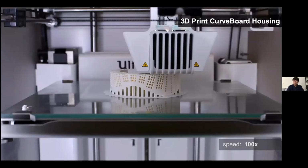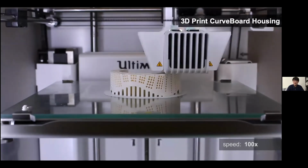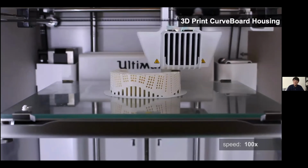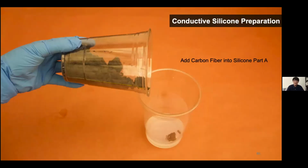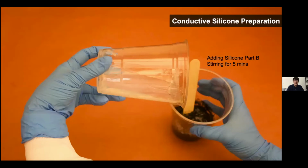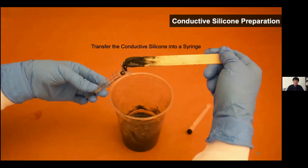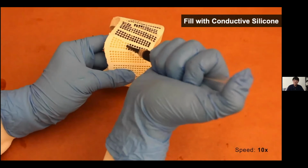This is the alternative technique that we use, with 3D printing plus conductive silicone. We will start by 3D printing the CurveBoard housing exported from the CurveBoard system. Then prepare the conductive silicone for injecting into the housing. To do so, we mix the carbon fiber into silicone part A first, stirring for 5 minutes, adding silicone part B, and stirring for another 5 minutes. Then transfer the made conductive silicone into a syringe. Then we fill the conductive silicone into the CurveBoard housing.